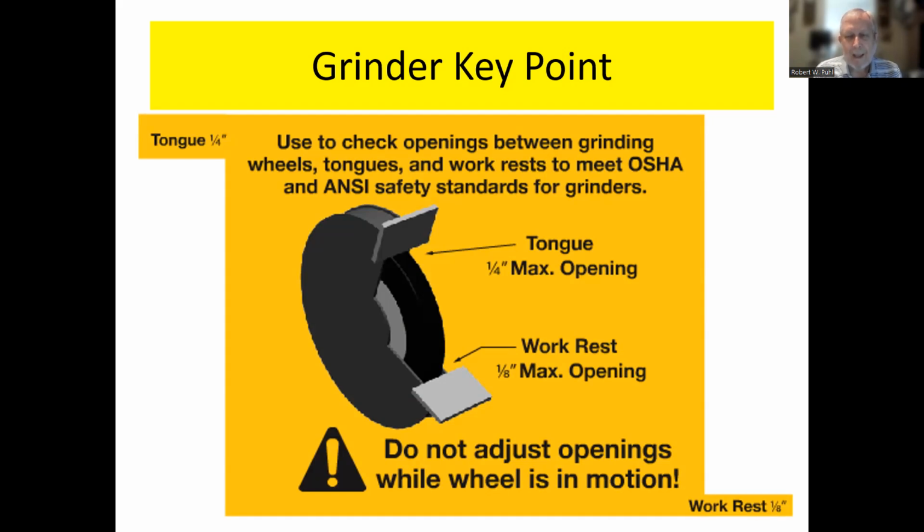Now you'll notice there's nothing on here about eye protection. Most of them have a shield that comes down, and usually they get so filthy after a while you can't even see through them. But there's nothing on here that says anything about eye protection, but you should be wearing eye protection when you are using these. Right? So don't take a grinder for granted. They can be pretty hazardous.